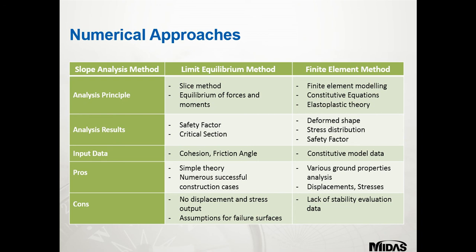So now just to focus on some of the pros and cons. For some of the pros, the LEM is more of an analytical approach for slope stability, and many practical cases exist where LEM has been used for slope stability analysis. In the FEM method, you can analyse different ground properties, for example effects of dilatancy on shear failure, and you can get the results for displacements and stresses as well.